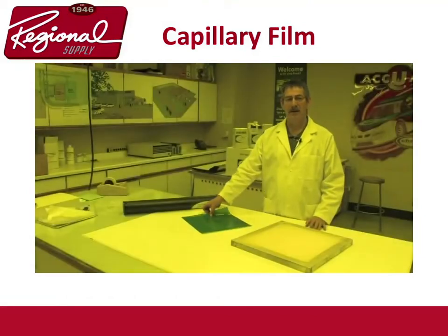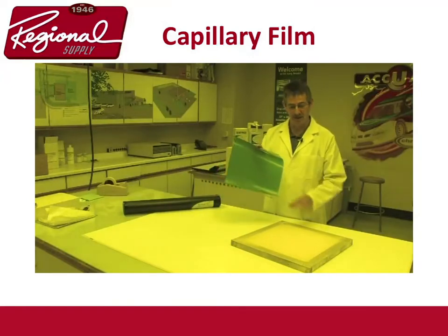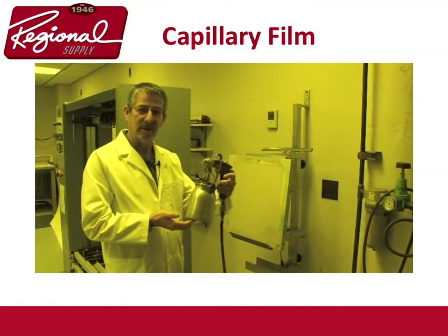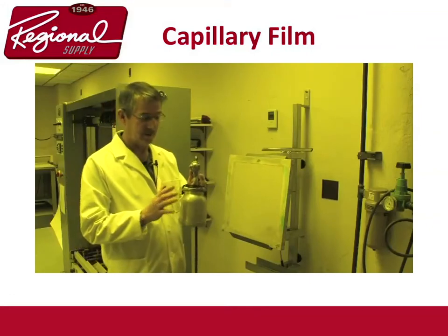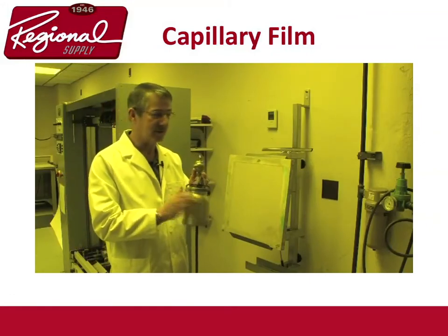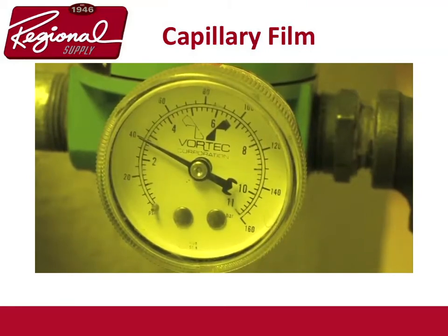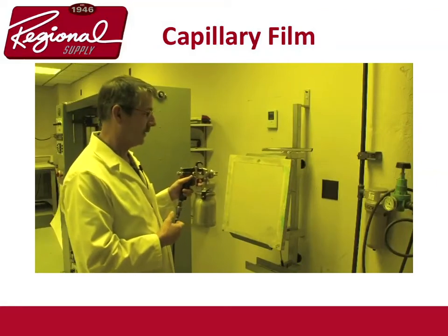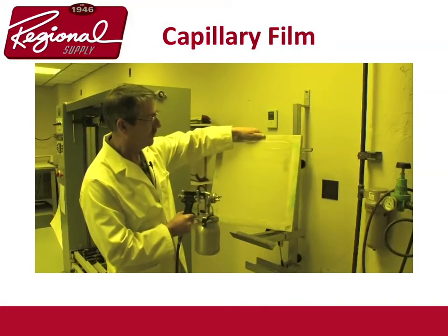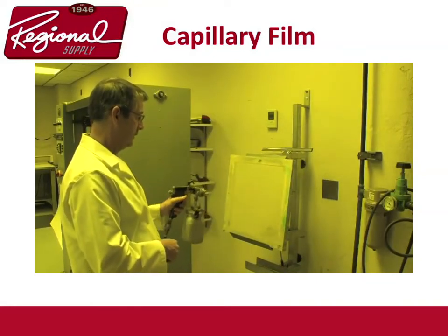Okay, now that we applied the roll down method, the next method is known as the spray gun method. I'm going to take this film and apply it to this screen using a spray gun. This is a typical spray gun you'd have if you were painting a car. What's important, number one, is you just have water in this canister and it be set between 30 and 40 pounds of air pressure. Now the first step is to put what's known as a light tack coat on the screen. You notice I have this screen facing print side out. I'll put a light tack coat on,